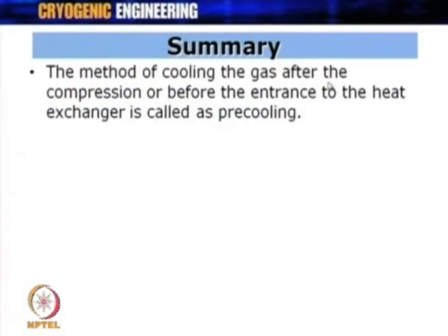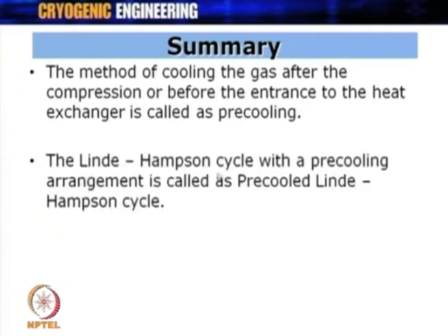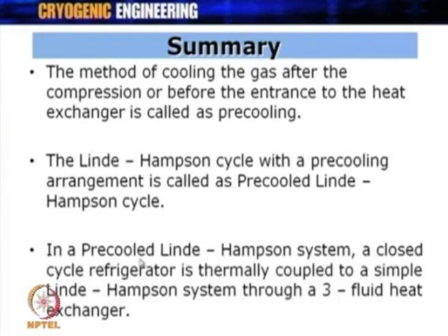In order to summarize what we have learned in this particular lecture, the method of cooling of the gas after the compression or before the entrance to the heat exchanger is what is called pre-cooling. The Linde-Hampson cycle with a pre-cooling arrangement is called the pre-cooled Linde-Hampson cycle. In a pre-cooled Linde-Hampson system, a closed cycle refrigerator is thermally coupled to a simple Linde-Hampson system through a 3-fluid heat exchanger.